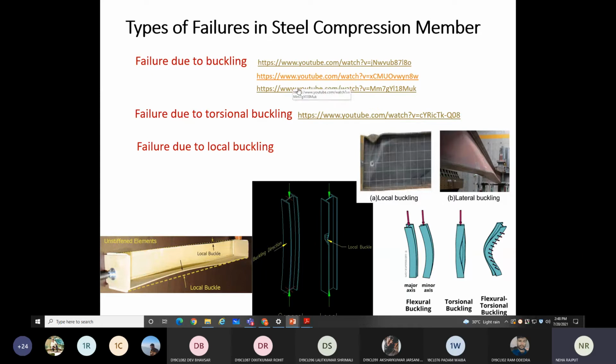Now in spite of only buckling, your members start rotating, and that buckling is known as torsional buckling. Here in the first three videos, only due to fixity at the support the column gets buckled, right? Only the buckling or the deflection is taking place, whereas in this condition not only translation but rotational movement will also be there in the column.